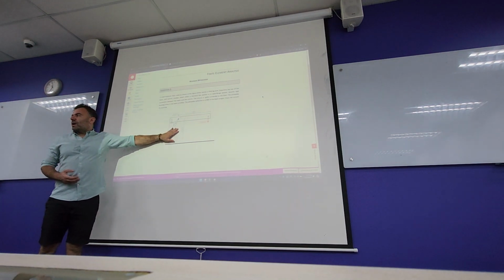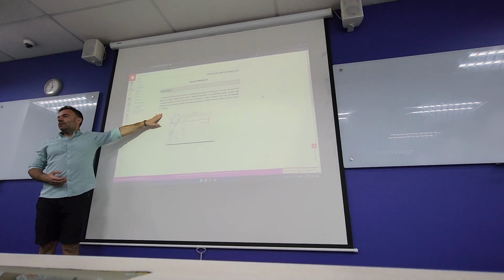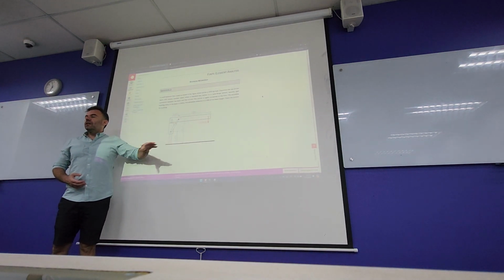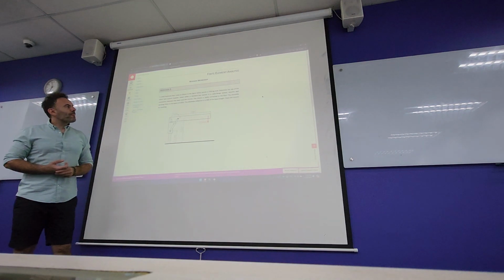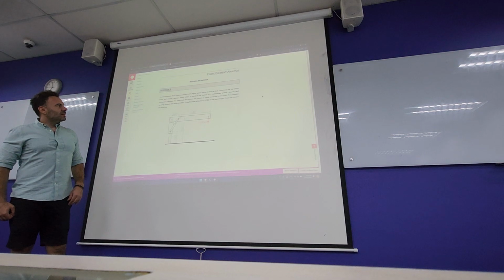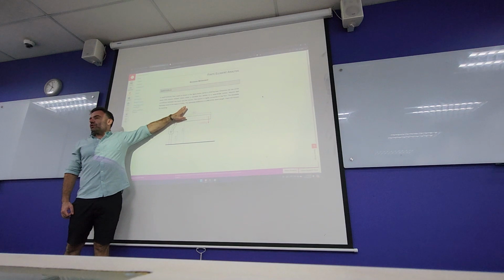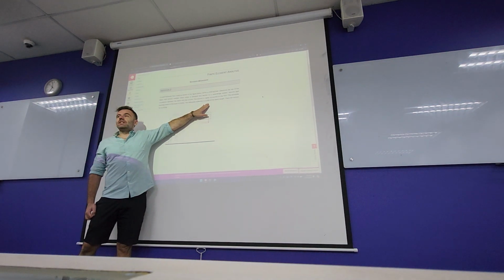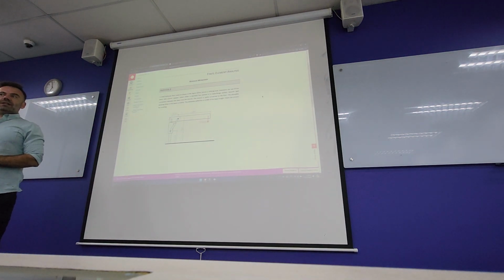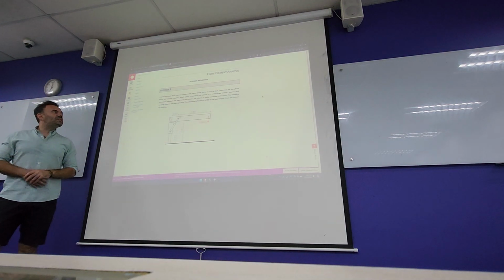Then once you run it, once you model it, then you have to go and interpret that. What are the relevant stresses? What are the relevant deflections? And what it means. Okay? So in this particular example, it tells you what are the limiting stresses. It tells you also what is the limiting deflection, so you can go and compare.